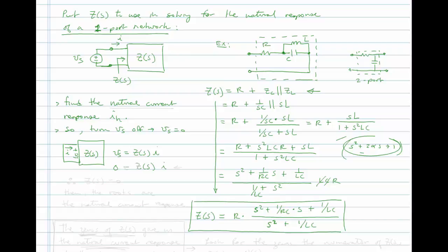Right? So what I find is that if there is any current that flows, if there is any possible current that could flow when there is no external excitation, it must be such that its value of S, or values of S, produce an impedance, Z sub S, that is actually equal to 0. So we would say, therefore, the only way that we can satisfy this, well, two ways. I could be 0, but the other way would be that Zs is equal to 0.